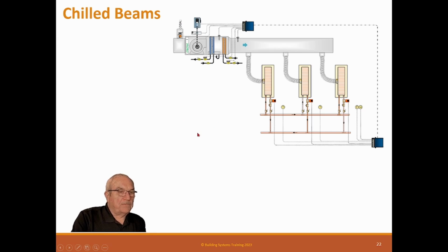Well, in some spaces they didn't have enough room, so they built a box beam and put it in the space, and they put chill ceiling panels on all three sides of the box beam, or in some cases all four sides, if it was exposed in the space. And they called it a chill beam, because it was actually a beam surrounded by panels.